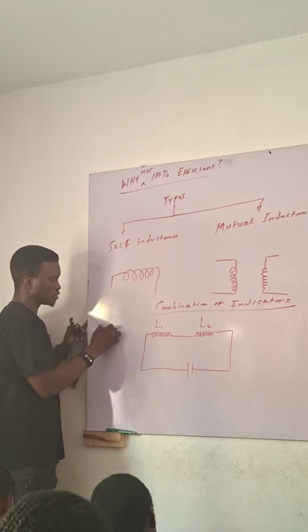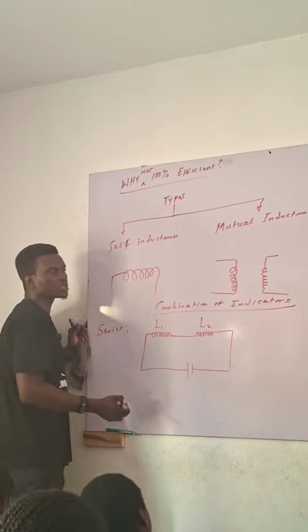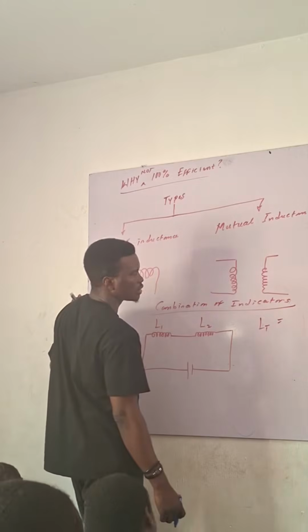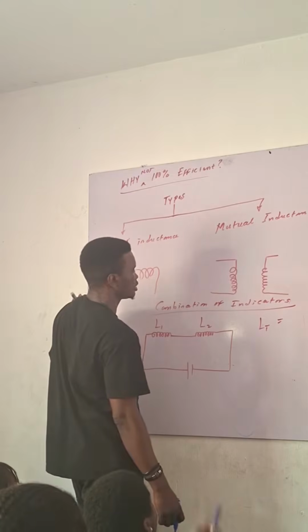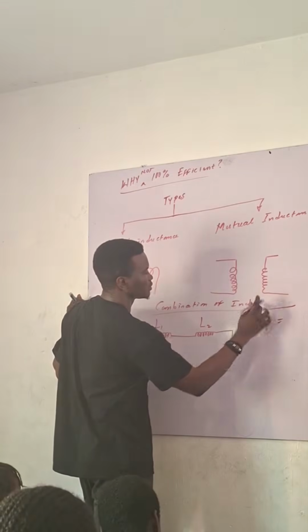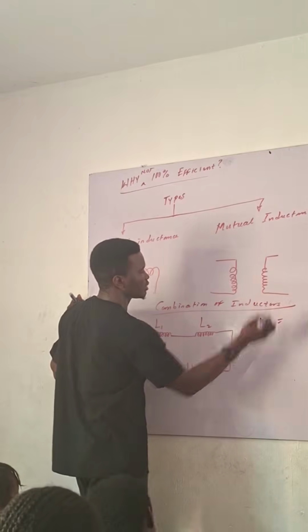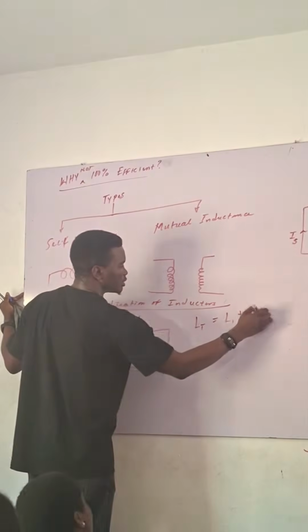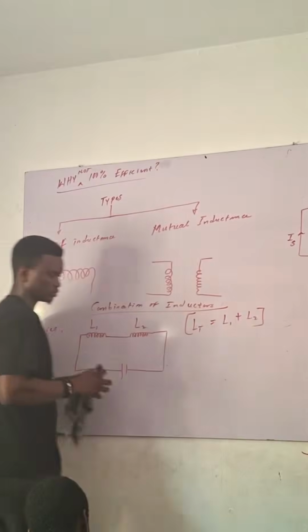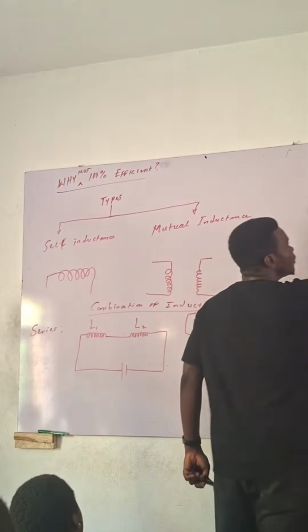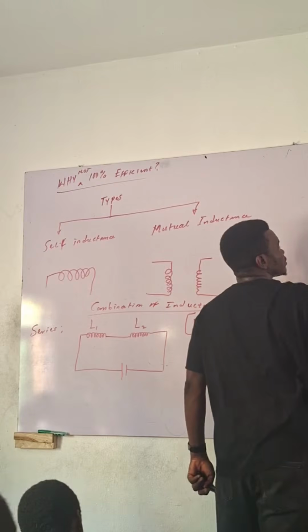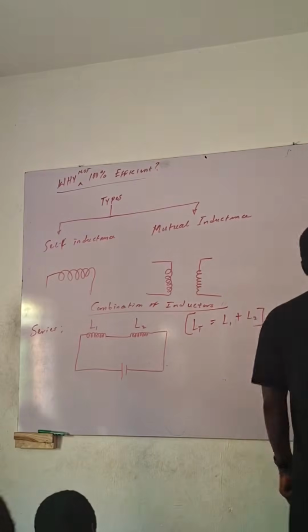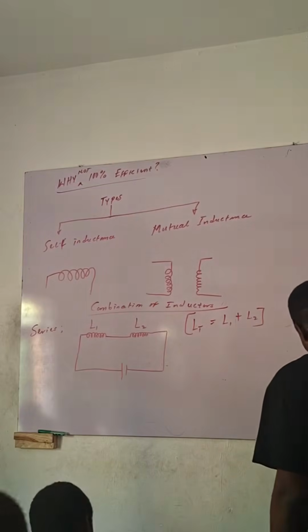When you combine inductors in series, you just add. I was testing you. So L total is going to be L1 plus L2.